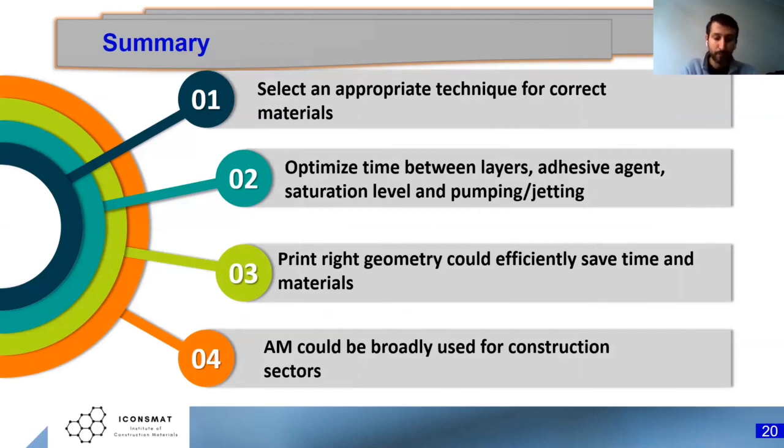Otherwise, it may not work properly, or it may take longer to achieve the property that you want. Especially for us as engineers, we are mostly focusing on mechanical properties, to get very high results in compressive strength and modulus of elasticity.